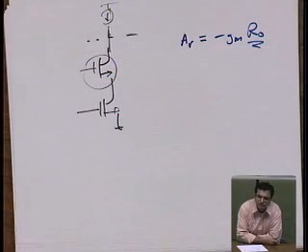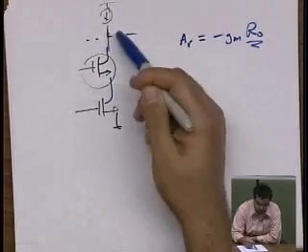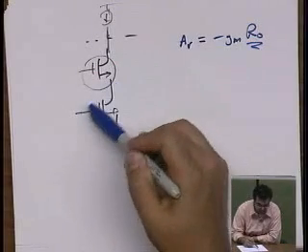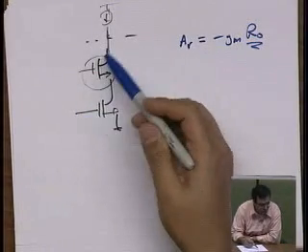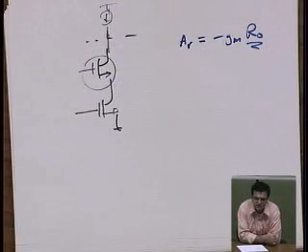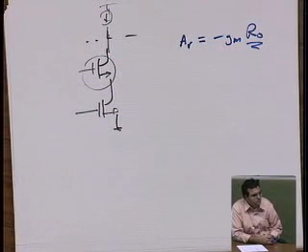Tim? It's unilateral. Yeah, it's more or less unilateral, and if you took 142, you know what that means. It means that the output and input are very well decoupled. If in a single common source amplifier you have this feedback capacitance, so the output and input are coupled. Here they're very well decoupled. What's the advantage of having it unilateral for analog circuits? Yes? There's no implicit feedback. Yeah, there's no bandwidth penalty, right?